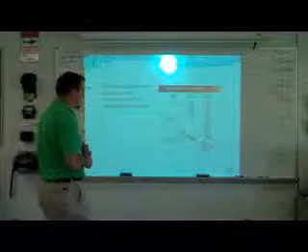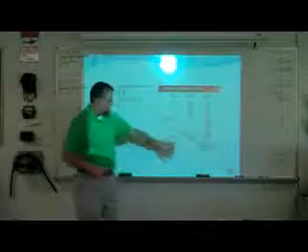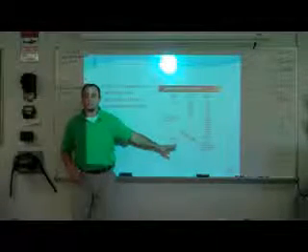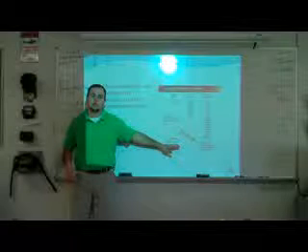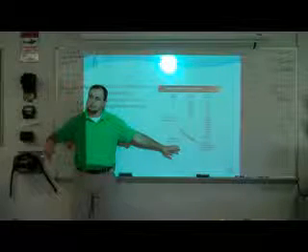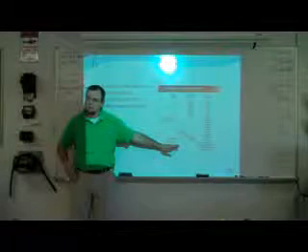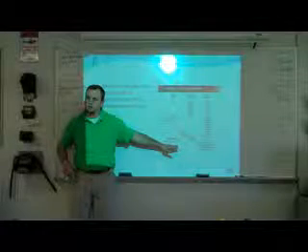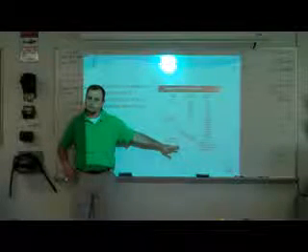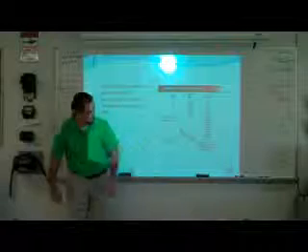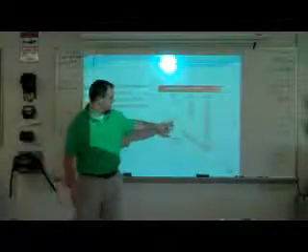So if you want to look at ampacity, in the 2008 it would be table 310.16. In the 2011, they got rid of this table and made it 310.15(B)(2)(a), I believe, is the table identification for that. Insulation is 310.13.